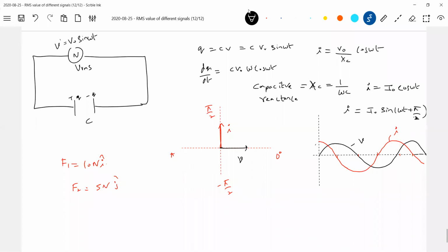So what about currents and voltages in an AC circuit? They are vectors, simplest way. Conclusion: you cannot take the algebraic sum. You have to take the vector sum of voltages or currents. Even the powers also here. In a phasor diagram, any quantity having a phase of 90 degrees will get aligned along the y-axis.